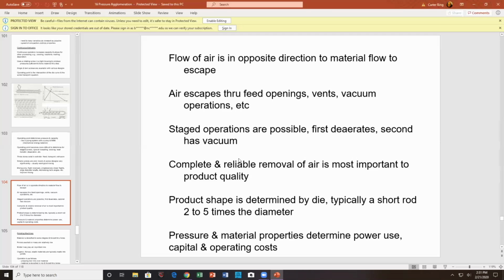So there's no logic in that. So what happens is you readjust your procedure to prevent problems from happening. Their aeration problem could have been avoided if they did the processing in an enclosed tank where there is no liquid surface for entrainment of gas, a totally enclosed tank. Then they could have mixed their emulsions, and they wouldn't have to wait 3 days for a separation to occur.